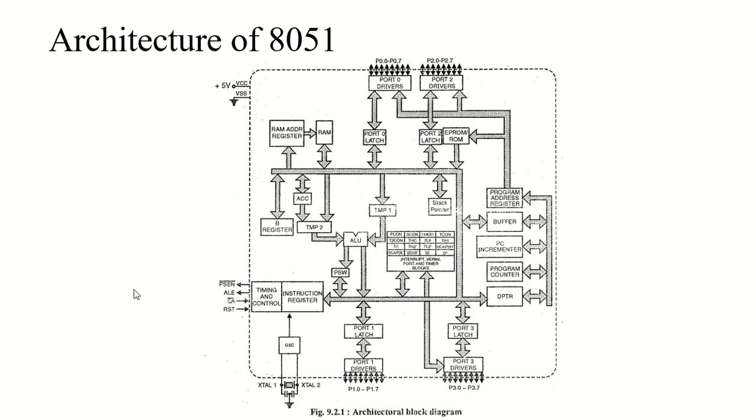The crystal frequency is the internal clock frequency of my microcontroller. Also, in the case of 8051 microcontrollers, the maximum operating frequency designed by the manufacturer ranges between 1 megahertz to 16 megahertz.